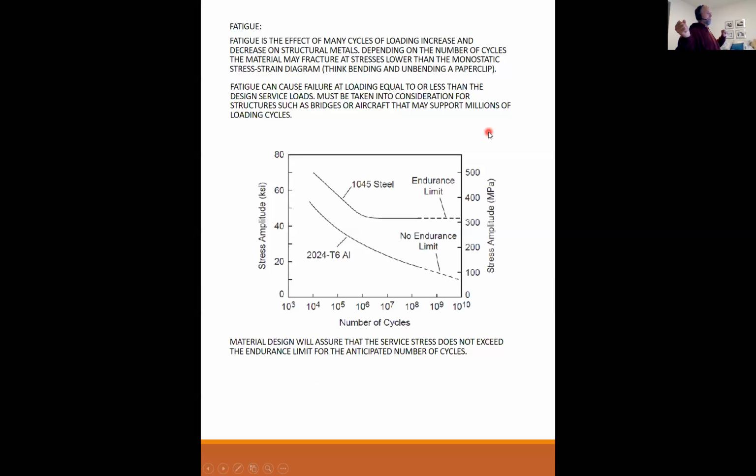Difference between G and E. One is a modulus of elasticity when you pull a material in the longitudinal direction. And the other, G, is the modulus of rigidity, which is a measure of the slope of elasticity, but in the shear direction. One's in the normal stress, one's a shear stress.